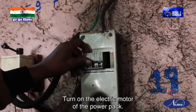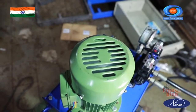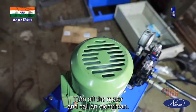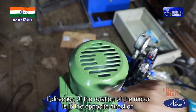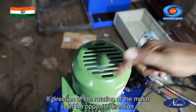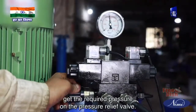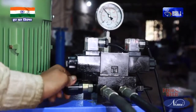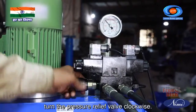Turn on the electric motor of the power pack. If the direction of rotation of the motor is opposite, turn off the motor and call an electrician. Get the required pressure on the pressure relief valve. To increase the pressure, turn the pressure relief valve clockwise.